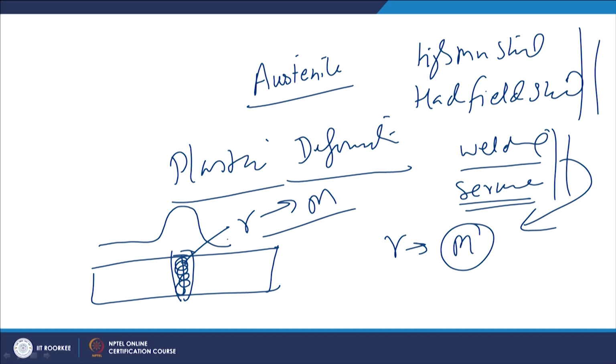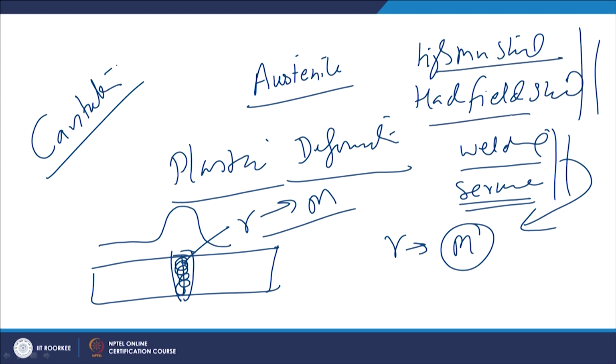So, here the plastic deformation is important, and such steels are very suitable for applications where cavitation is involved, like in fluid flow systems where cavitation causes loss of material. Cavitation develops the impact of high pressure waves on the steel, leading to controlled surface layer deformation, and the surface deformation associated with the austenite to martensite transformation increases the hardness, and thereby helps in reducing the erosion of the material.